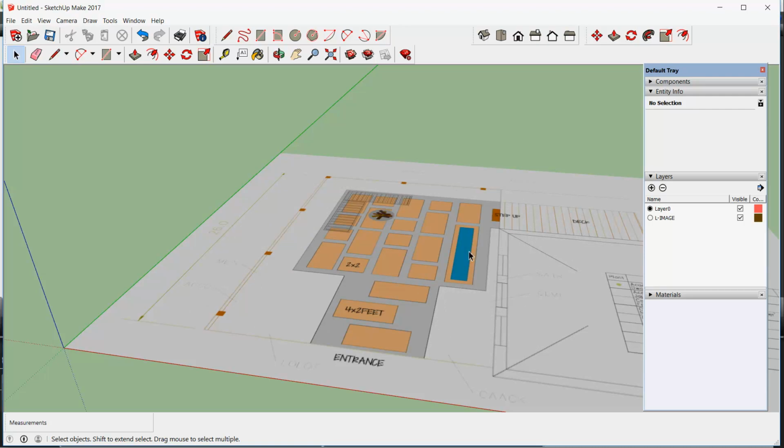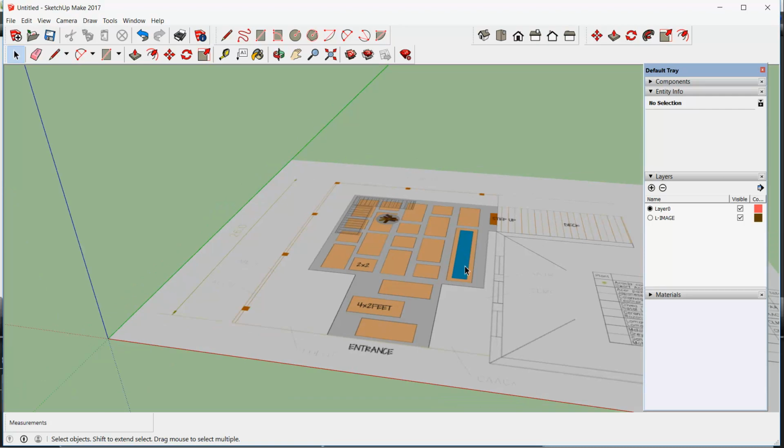Now you'll notice that there's an ornamental pond running along the side near the building there, and we'll want to put a rectangle over that and push that down. To that end, I think it's a useful thing to do at this stage to select the image, and we'll just move it up a short distance, maybe a foot above the horizontal plane, and then we can push the pond down quite easily, and it will go down underneath the level that the image file is on.